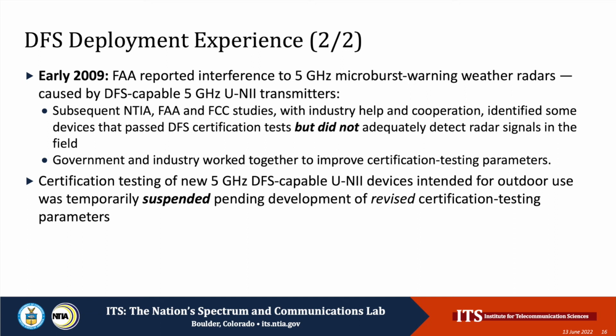The essence of the problem overall was this. Way back in the formative stages for the technology, when inquiries had been made as to the exact technical parameters of the radars that would need to be detected at 5 GHz, there was a disconnect that occurred at the human level between the actual parameters of the radars in the band and the set of parameters that was made available for the testing. This disconnect resulted in the original initial certification testing not always using the actual parameters of radar pulses that were operating in the 5 GHz band.